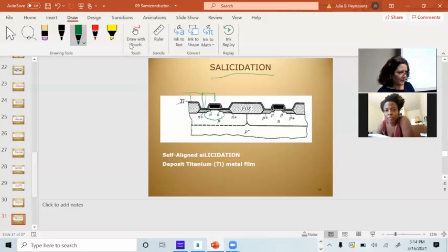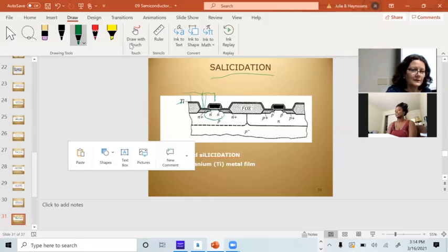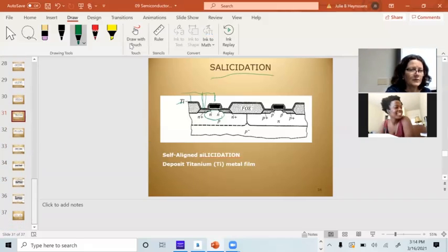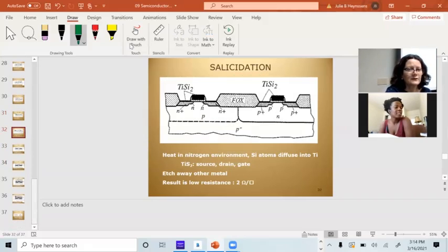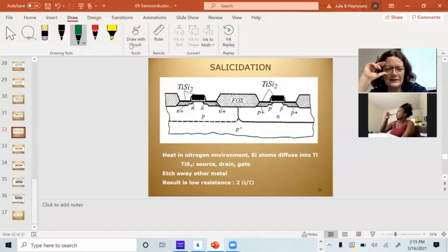Now, one thing that was horrible about our IR arrays is that astronomers in general did not like passivation, partially because the IR photons would not go through it. So we had to leave them all bare. And we had to keep everything in a nitrogen-filled tank when it wasn't inside a vacuum chamber, to keep the oxide from growing on it, and handle them quickly. The technicians couldn't handle the nitrogen environment, unfortunately.